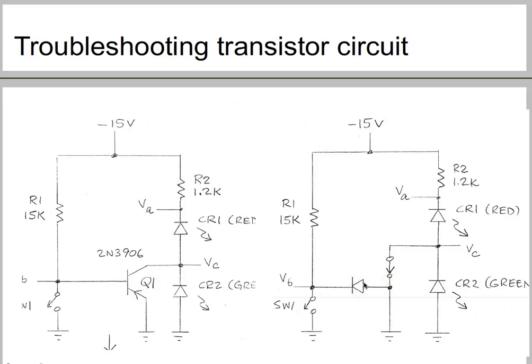This should be checked by multiplying the base current by 20. If that is greater than IC, then it is in saturation mode, and if it is not, then it will be in linear mode. So when Q1 is on, there is a short from the collector to emitter, which should turn CR2 off. This CR2 is your green LED. This will be off since it is shorted out.